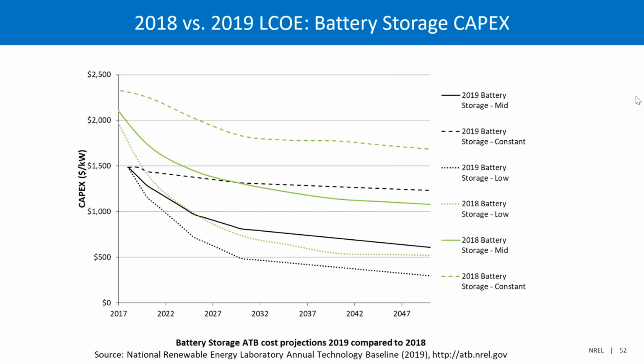That's a good question, and realistically there is a specific tower cost formula in SAM, the System Advisor Model, and that's based on today's technologies, not things like additively constructed towers. So it's based on empirical data from real plants that were constructed, and then you have a formula which effectively scales based on the height that you request and based on the power that you need for your site.